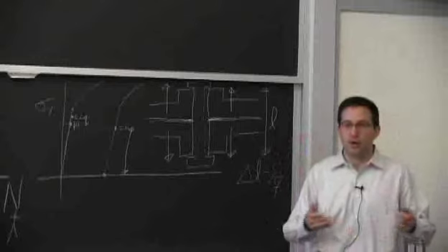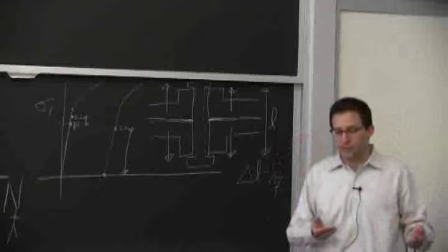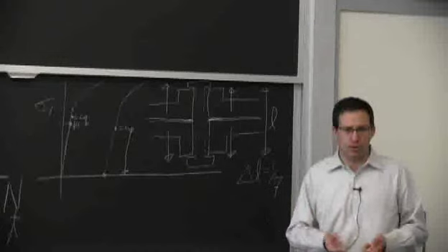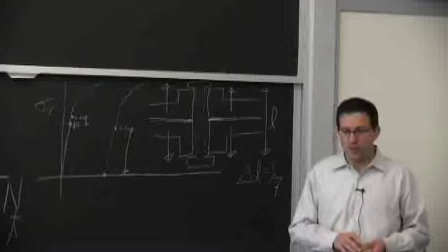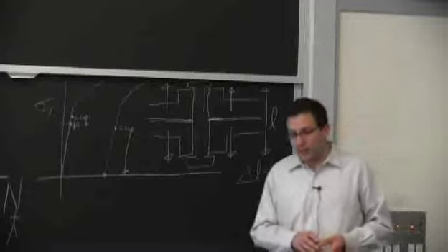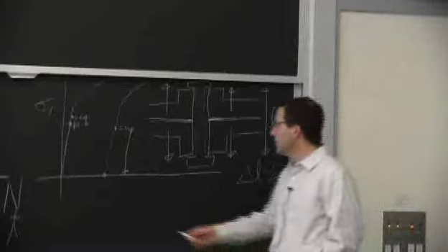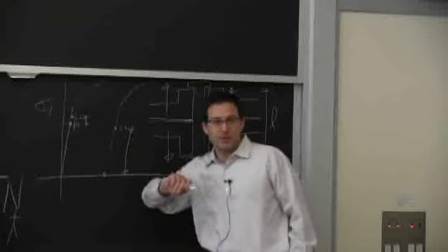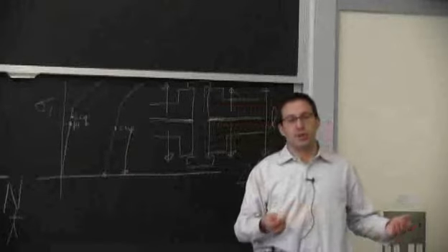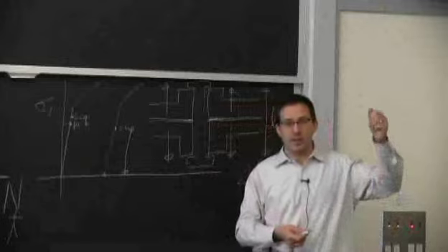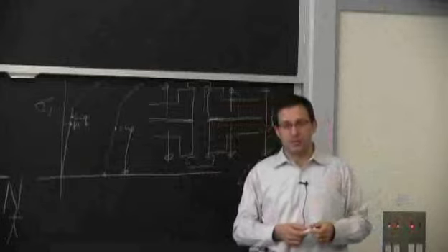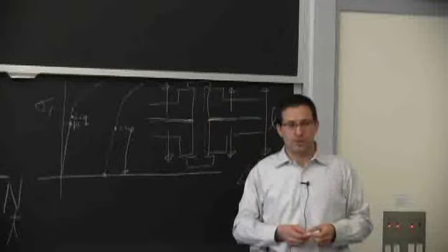And you have to draw one for different number of cycles to failure that you may consider. It's useful for bolts, because clearly they have a preload. So you can't go and take an experiment that was done going in tension compression and design based on that. You have to draw the diagram to get to the properties.